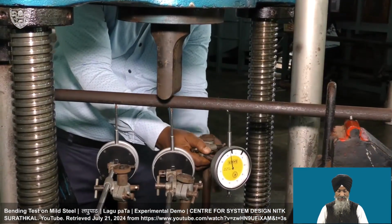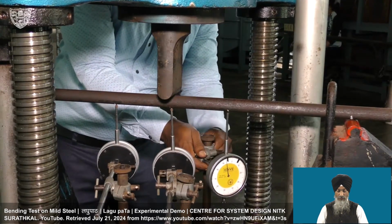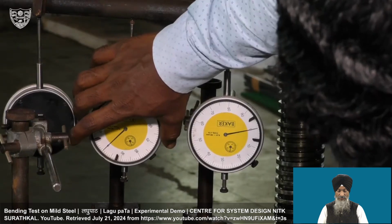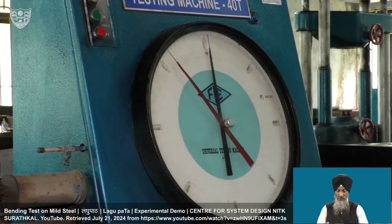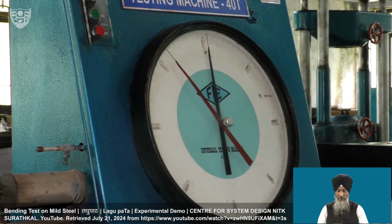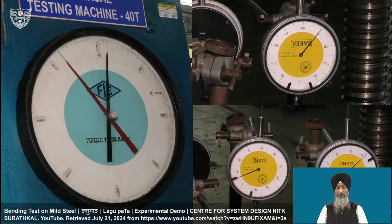Now, we adjust the dial gauge readings to 0 and switch on the machine. Once the machine is switched on, gradual loading begins. We see the 1/3 span and the mid span dial gauges showing readings, and there is also a load being applied here.